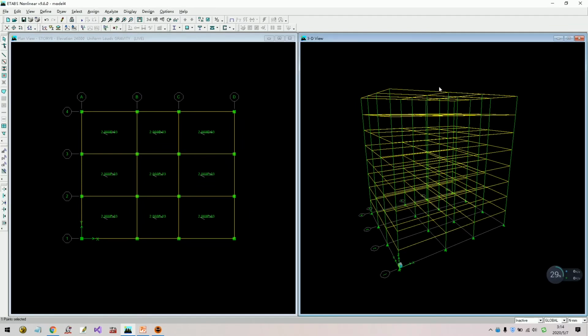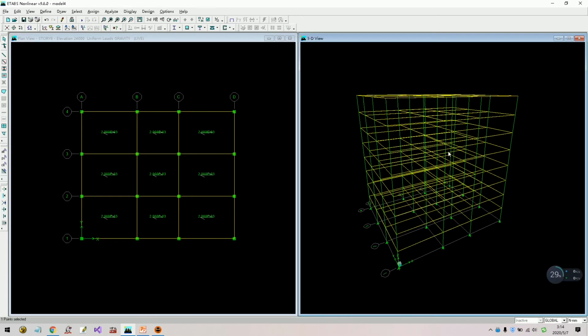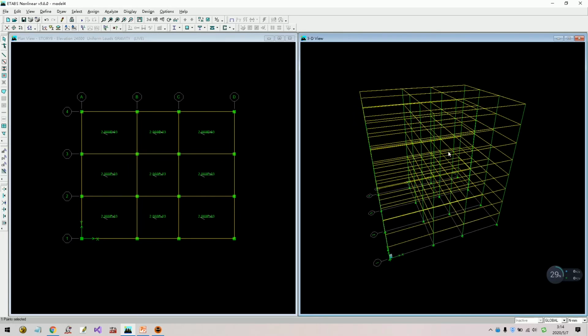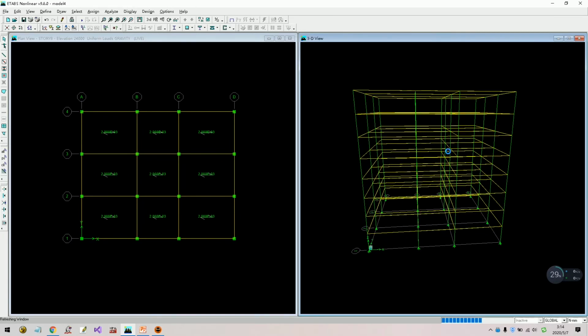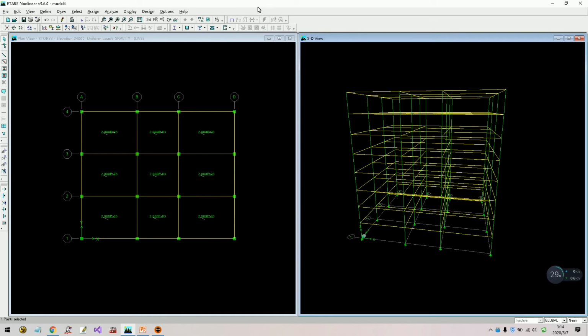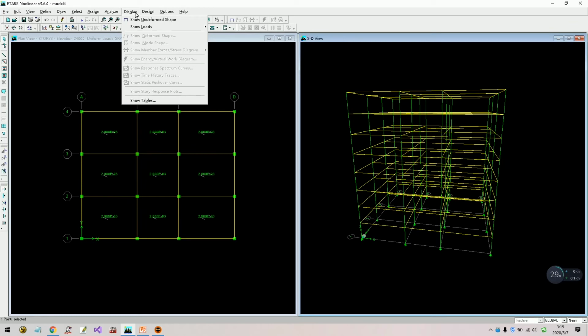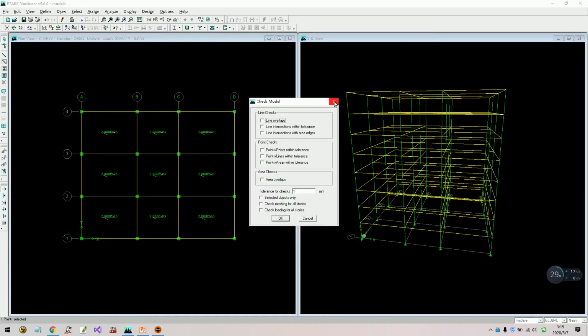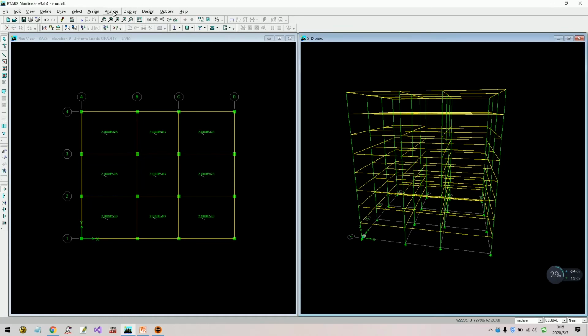So, when we have the stiffness matrix and the mass matrix, we can run the modal analysis, because this is an NDOF system. Even for a single story, it has more than one DOF, so it's a lot of DOF. So we can run maybe hundreds or thousands of modes, but actually we just need quite a few.